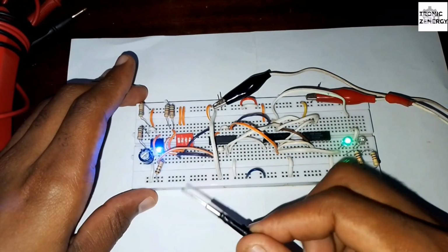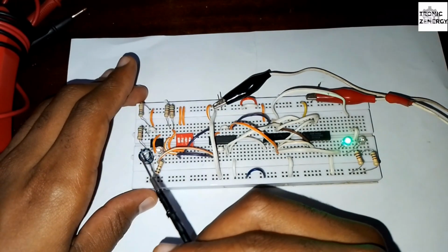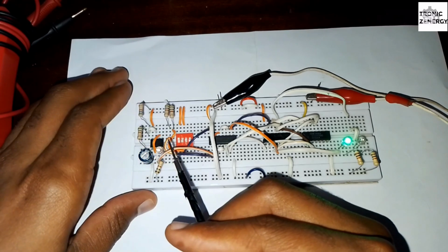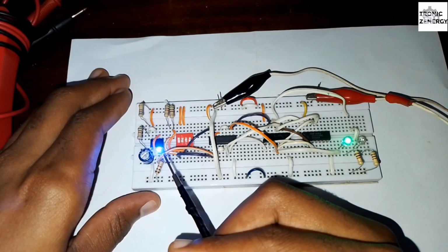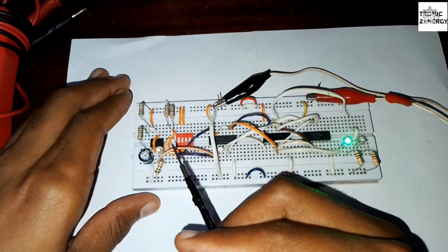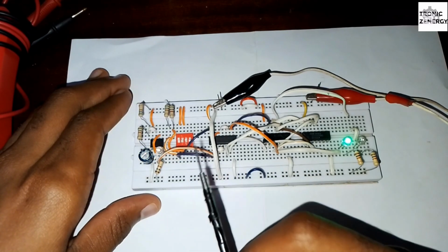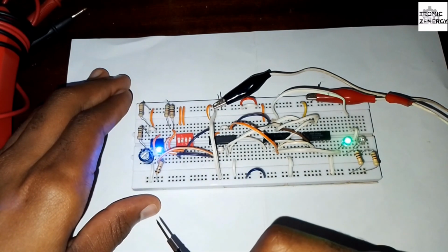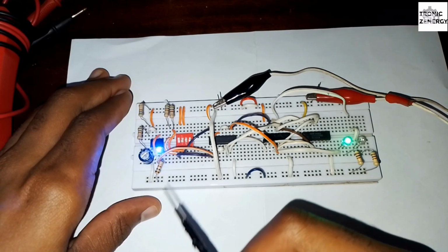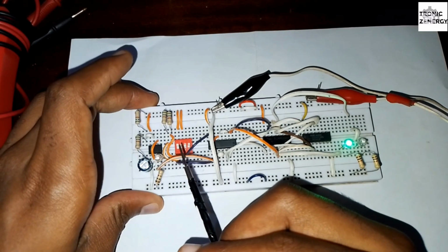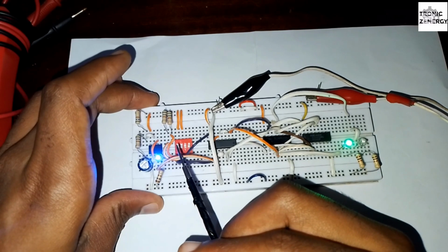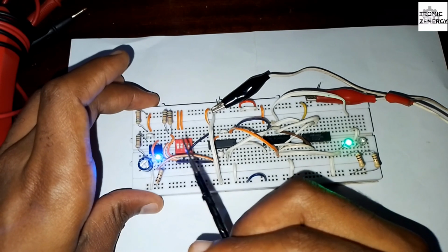So here we have this section right here, which is the clock. You can see the LED turning on and off. It's the clock that's going to be used at the input section of those NAND gates. And right here we have the switch. It's a DIP switch. I'm using these two fast switches. The first one is J, the other one is K.